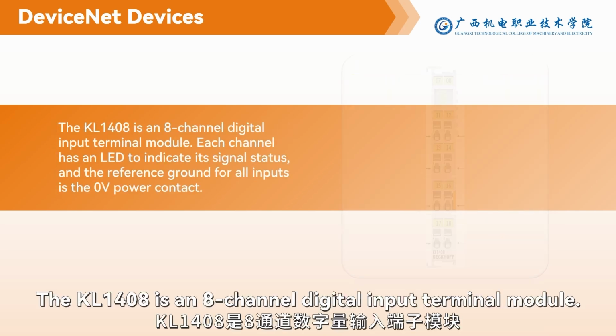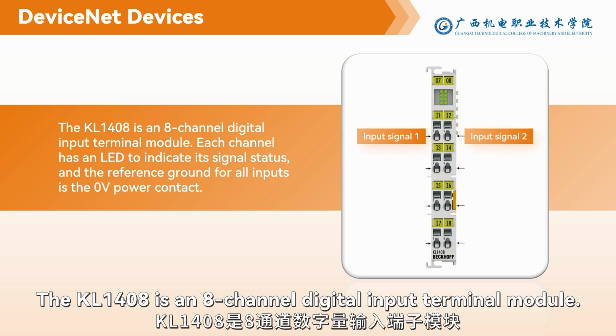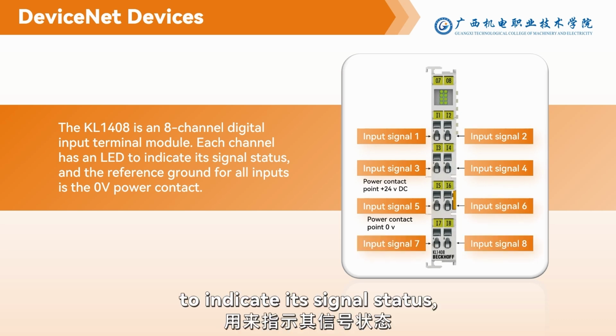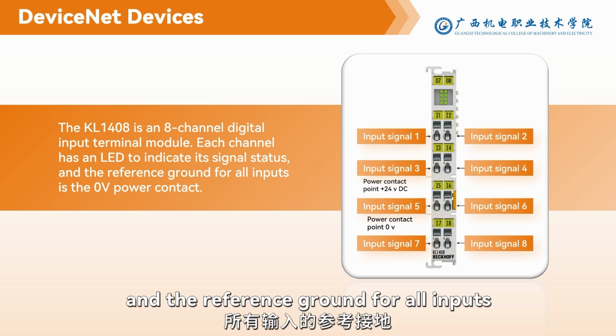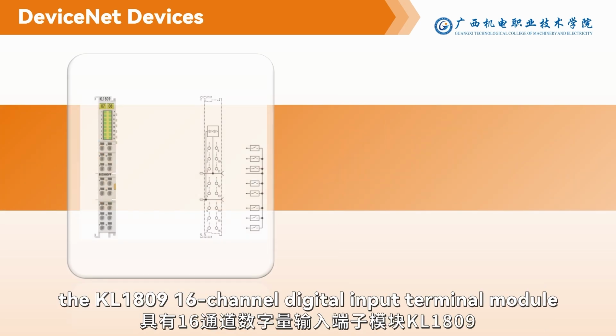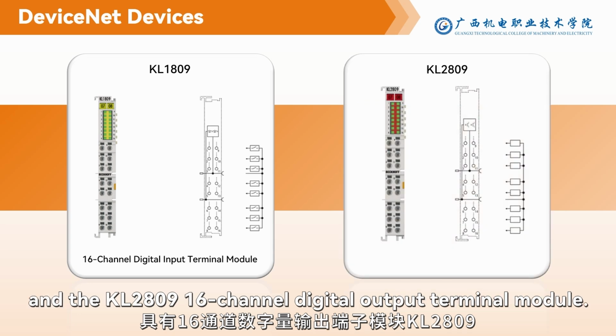The KL1408 is an 8-channel digital input terminal model. Each channel has an LED to indicate its signal state, and the reference ground for all inputs is the 0-volt power contact. We also use the KL1A09 16-channel digital input terminal model and the KL2A09 16-channel digital output terminal model.